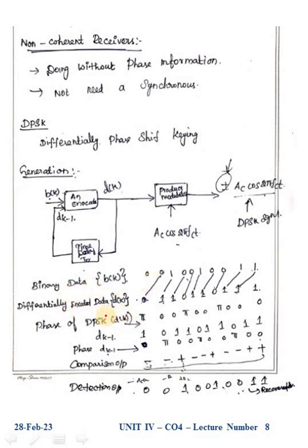Then we have to identify the phase of DPSK. To obtain this dk, I have given the formula in DPSK; please refer to that formula. For the phase of DPSK, you compare the binary data with the encoded data value. If both are 0, the phase shift is considered as pi, and if they are different, then the phase value is 0.